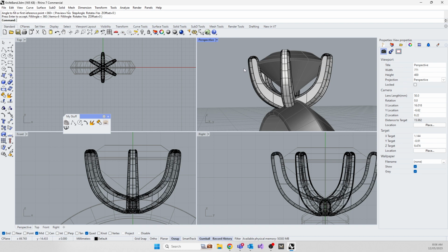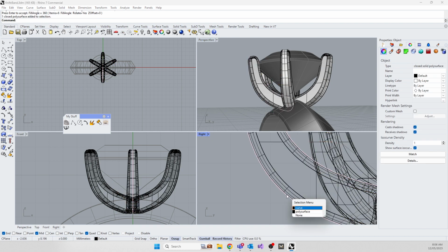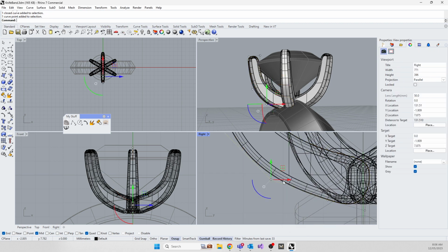Nice. As soon as you did this fillet, it means that this part no longer listens to that curve. You would have got a warning saying that the history is no longer valid. So if you change this now, nothing's changing. So you'd have to go back, curve, extrude again, fillet again. Otherwise, the tool that we learned yesterday.